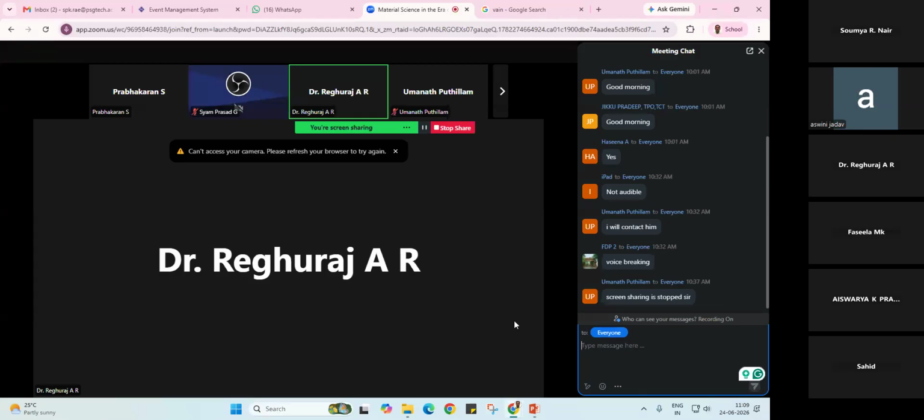You will have high surface roughness value. So if you want to make bio implants, it is better to go with powder bed additive manufacturing, which you called as SLM. Right? I didn't discuss that, sir, in this lecture. But we have one machine on our campus that has the capability to print bio implants.